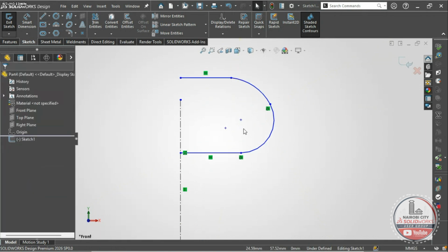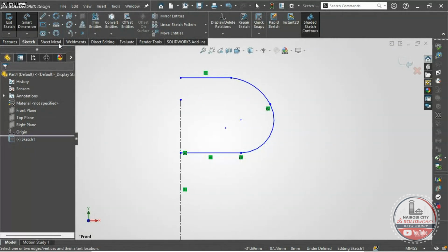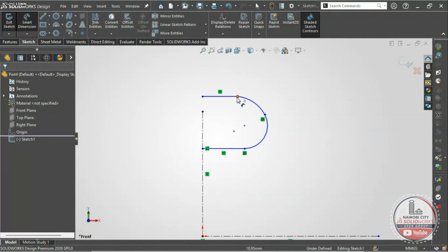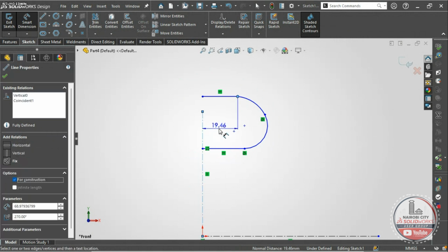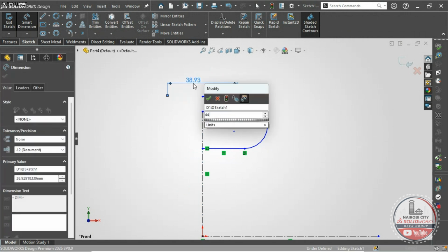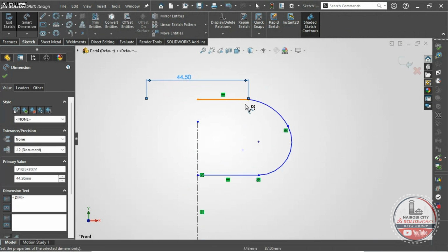So for example, I just have something related to this. So my main focus is to draw something related to this. So you find that here the center distance is 44.5. When you come to dimensions, you tap onto this edge center line. When you are on one side, it brings on one side, but when you cross and are on both sides, it brings the dimension you want, which is 44.5. So I just have something related with that at first.